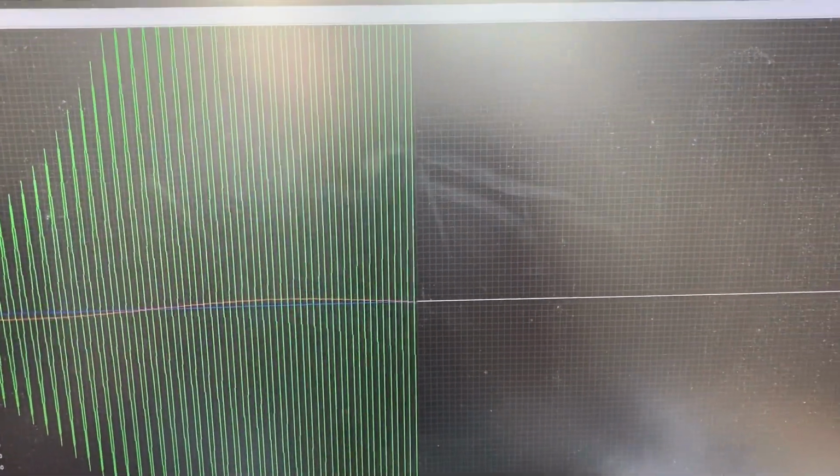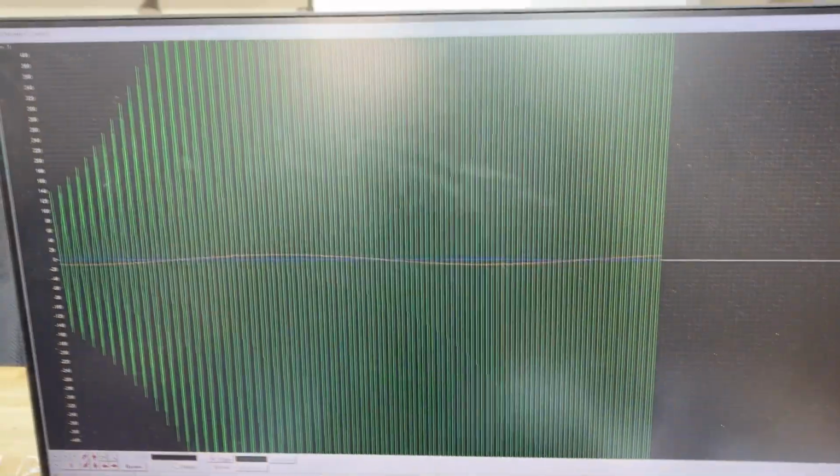As you can see, the filter input is still bounded. It's just a simple sinusoid with a fixed magnitude, but the output is growing until the floating point variable is saturated. And this really nicely confirms our Z transform theory that we can see when filters become unstable and when they are stable themselves. So this is pretty cool to see.